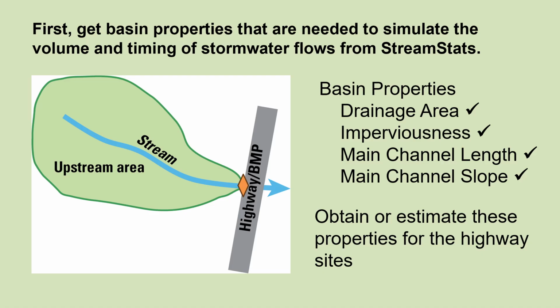SELDM is simulating long-term populations of runoff generating events, and so it's important that we can translate precipitation statistics into the amount of stormwater flow, as well as at what point or how much of that flow is concurrently being discharged from the highway and the upstream basin.